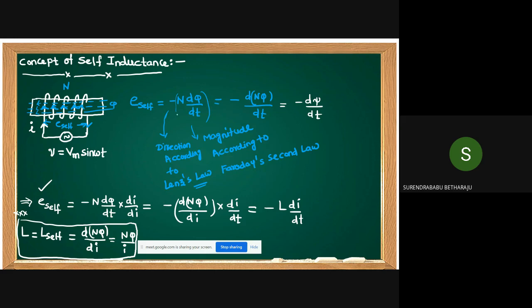Sir, why this negative sign, sir? It is according to Lenz's law. What does Lenz's law state? The response always opposes the cause. Who is the response here? Induced EMF is the response. Who is the cause here? Change of flux. According to Lenz's law, the induced EMF always opposes the rate of change of flux.